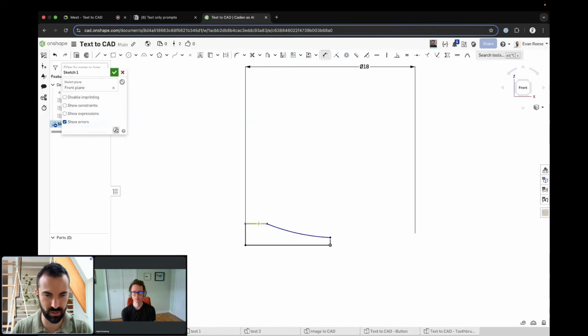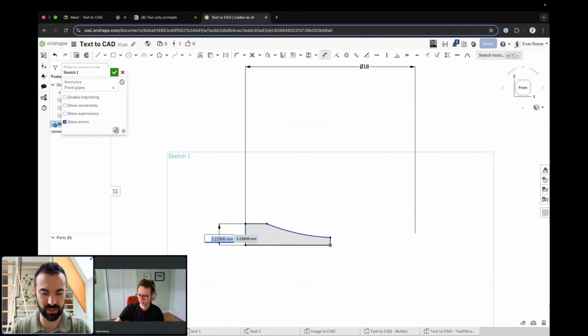There's no thickness, so I'm just going to guess. Again, I'm using my human experience of buttons to make an assumption about how thick this would have to be, but the AI probably isn't going to know that. So I'm going to guess that a shirt button is like 3 or 4 millimeters thick. So I'm going to make this like 1.75, and that's the half of it.